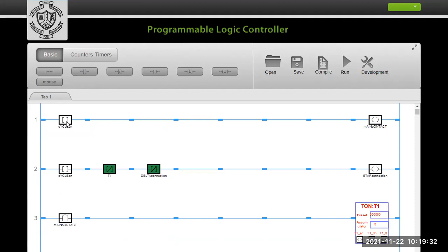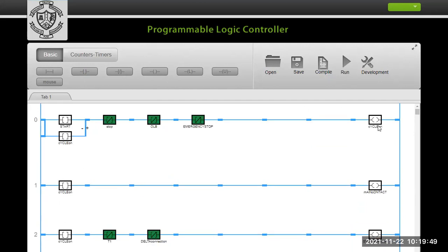Whenever the cycle is going on, your main contact is also in the making position, because this is your cycle on, and this is your main contact, this is your real contact. These are the cycle on, this type of undergoing NO and NC. This is the virtual NO and NC. It does not exist in your circuit components, but it will exist in your PLC programming. So there are some real contacts, real inputs and outputs, and some are virtual.